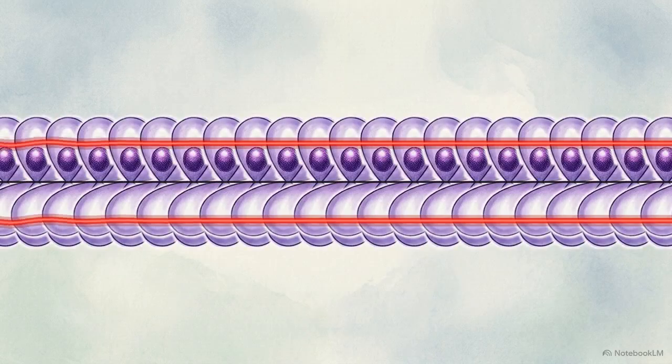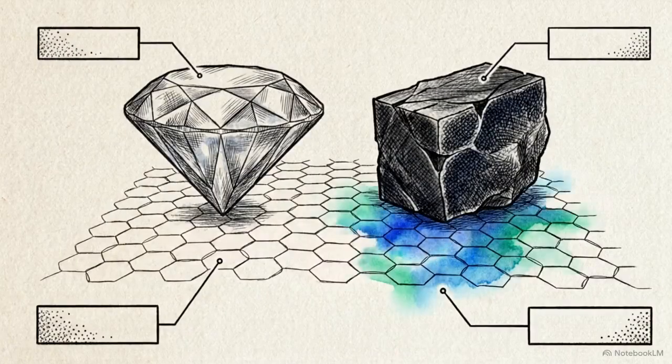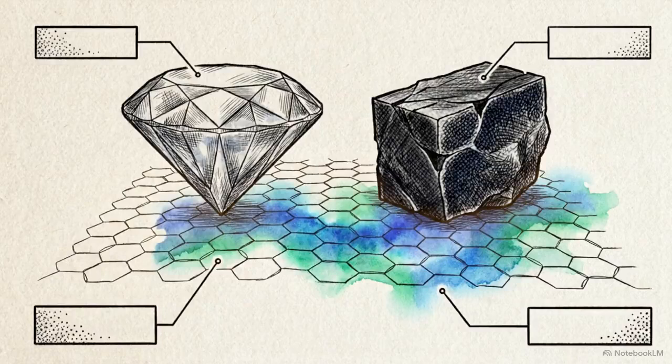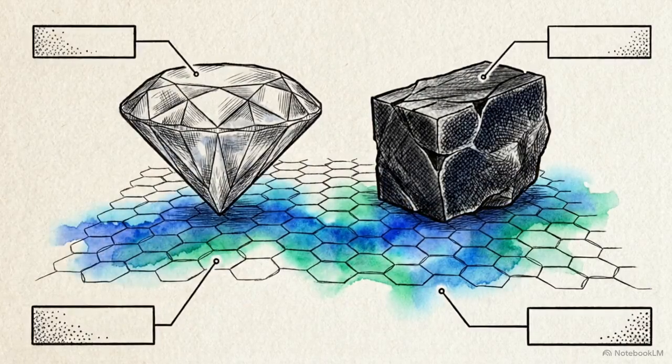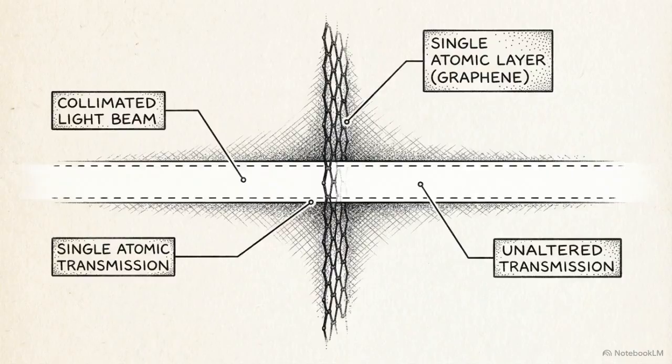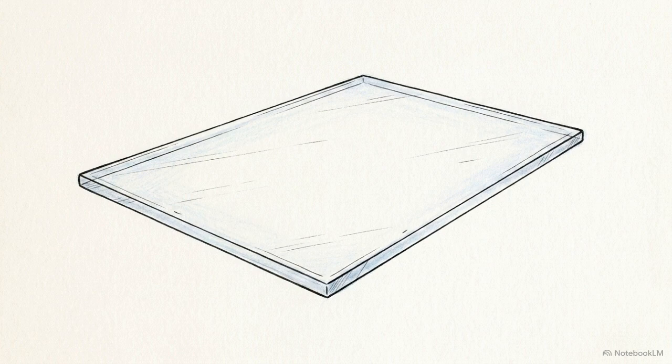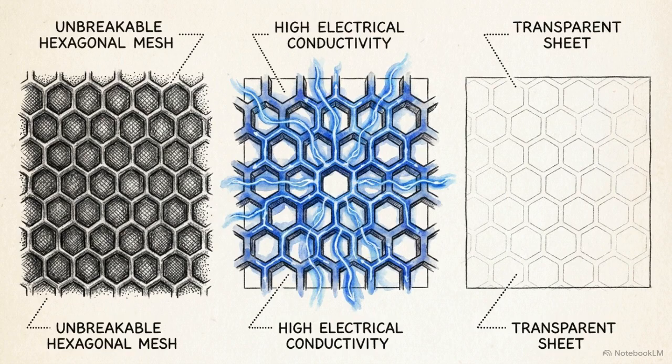The same continuous band structure provides a pathway for heat dissipation. Phonons travel so incredibly efficiently through the lattice that graphene's thermal conductivity surpasses both diamond and bulk graphite. Optically, the thinness of the atomic sheet means it interacts minimally with photons. The material absorbs only 2.3% of white light, giving it a transmittance rate of 97.7%. The same perpendicular pi band architecture that provides extreme structural strength also enables conductivity beyond copper and near total optical transparency.